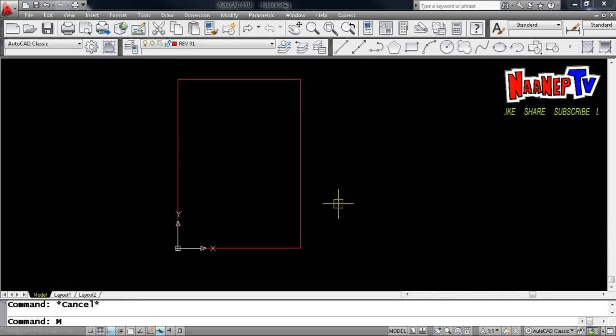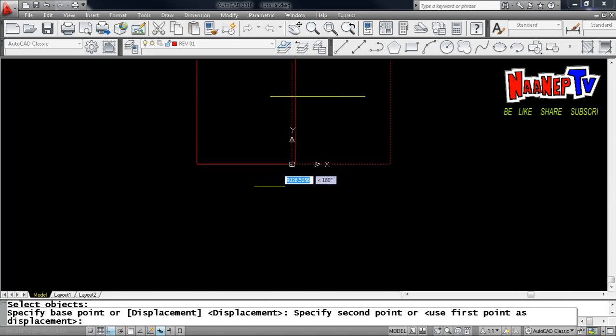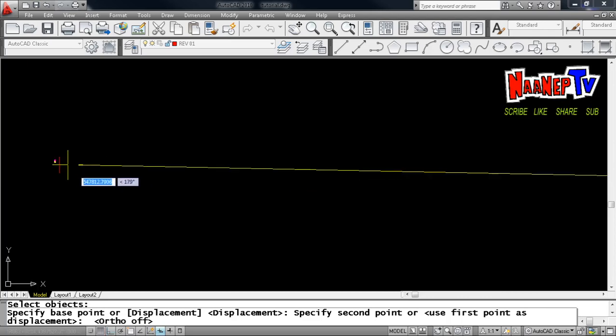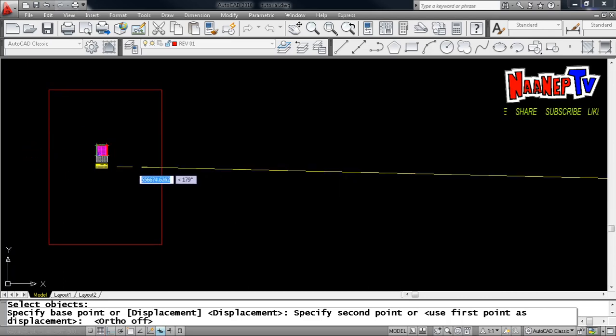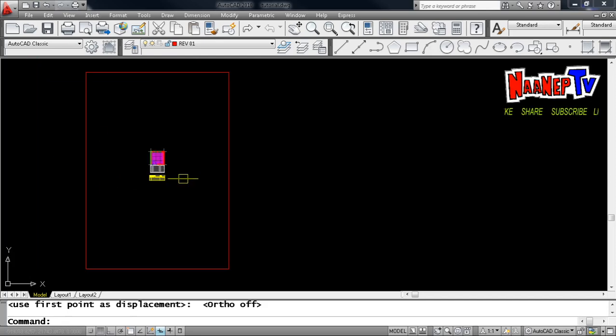We already have the paper in the upright position. It always goes back to 0,0, so you have to drag it here. Now you can see, if you require a scale of 1:50 and the paper that you're going to use is A4 size, it will be printed out this size. So we try again and adjust. Maybe we try 1:10.